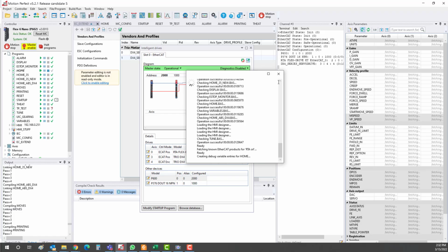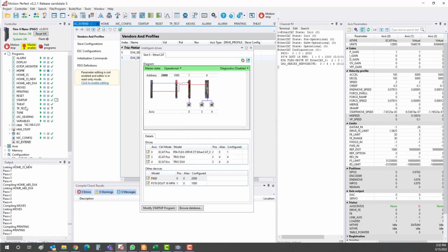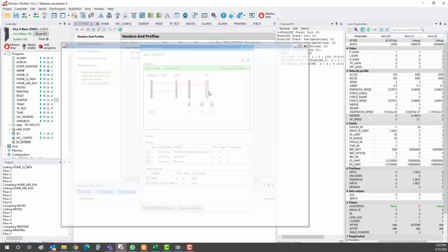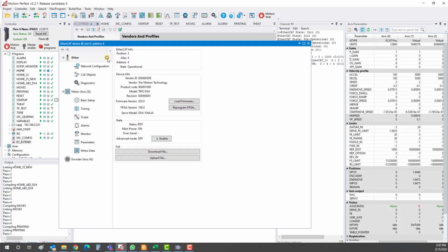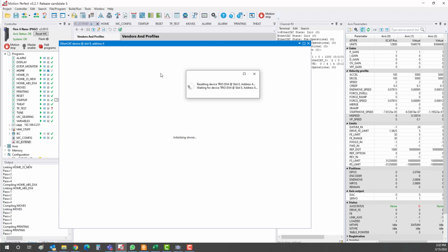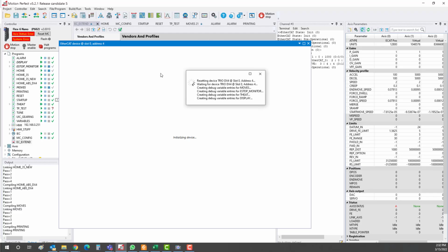Yeah, because my startup program actually does the servo on the axis, so I need to servo off and then go to the menu. I restart the servo like this. You can do it by physical cycle power also. That's also the hard way, but the soft, easier way is to use the button over here to do that.